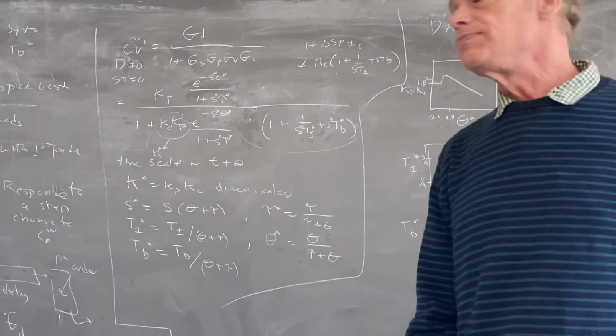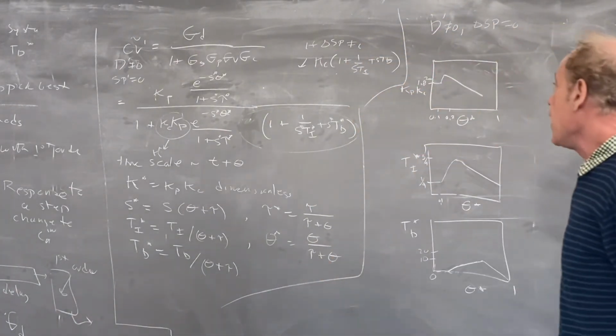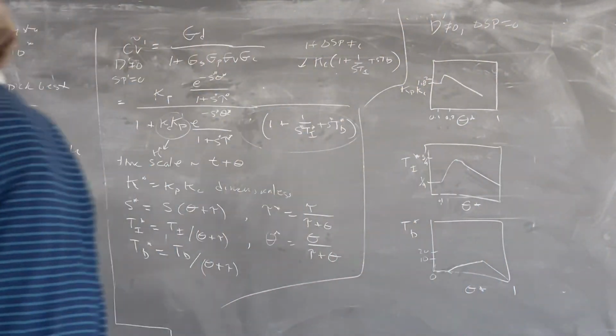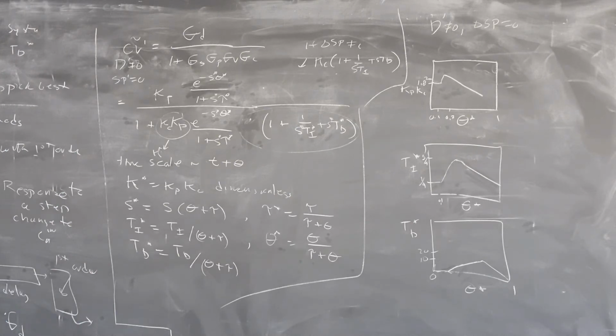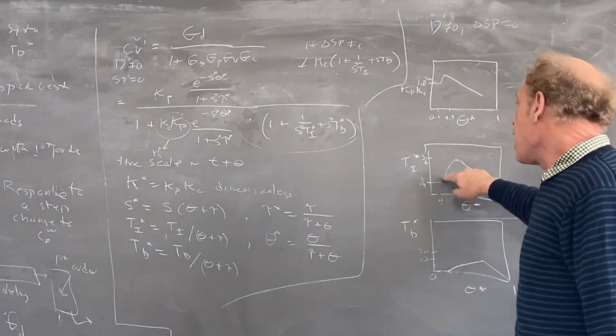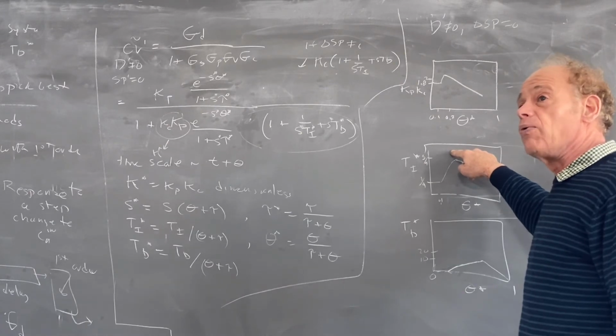Now what happens with TI? Once I have KC getting large, well, again, the proportional controller never gets rid of the offset. I never get to the temperature I like. So initially, once I am having the proportional control on, I also kick on the integral control to get rid of the offset. So I get where I'm going.